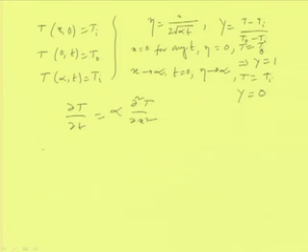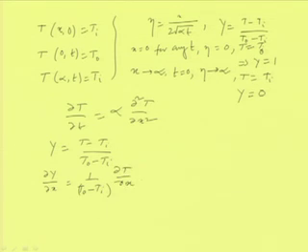So, say y = (T − Ti)/(To − Ti), and then ∂y/∂x = 1/(To − Ti) × ∂T/∂x. And we know that η = x/(2√(αt)), then we can get ∂η/∂x = 1/(2√(αt)).